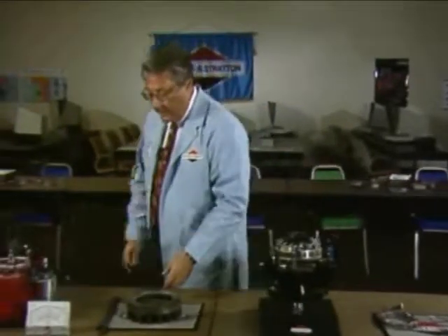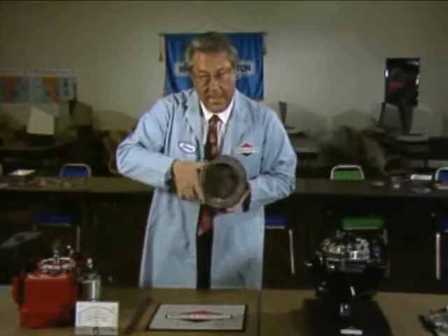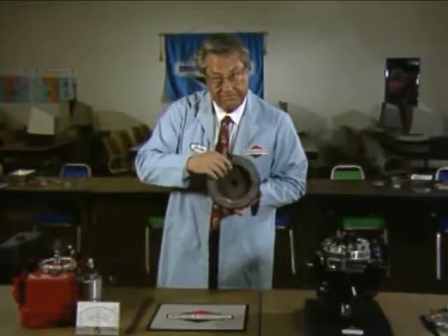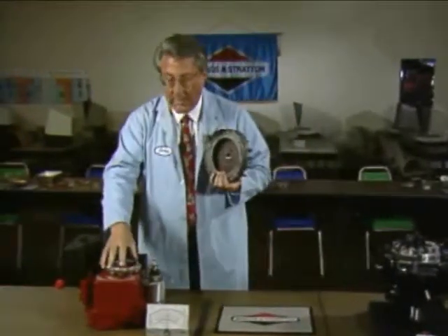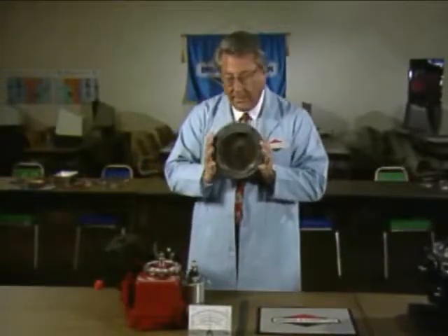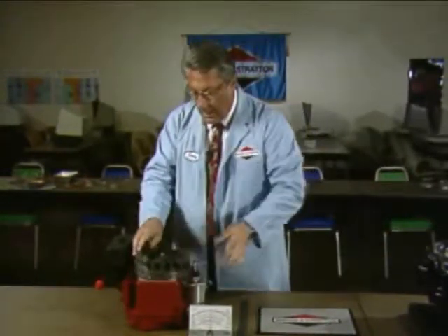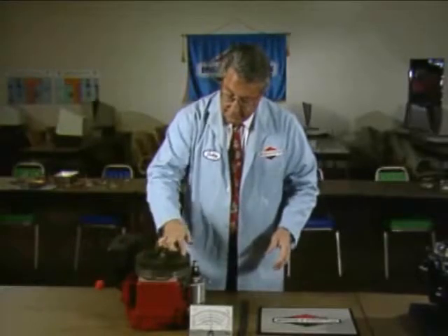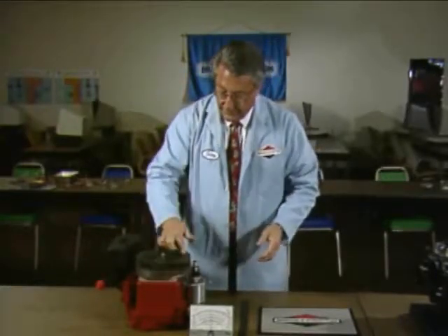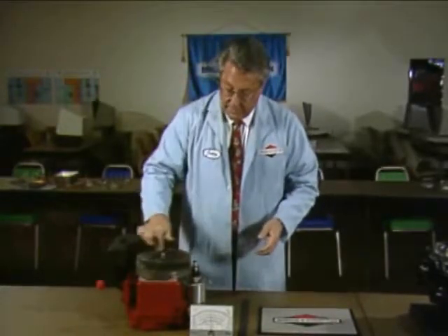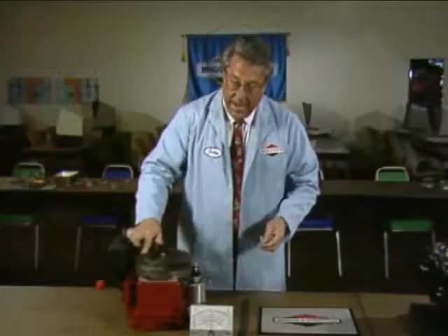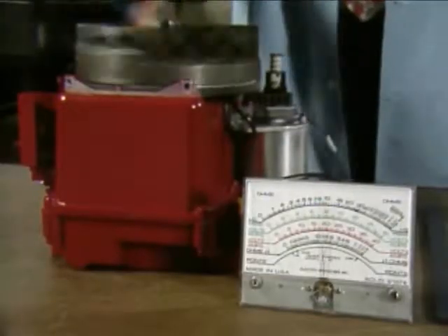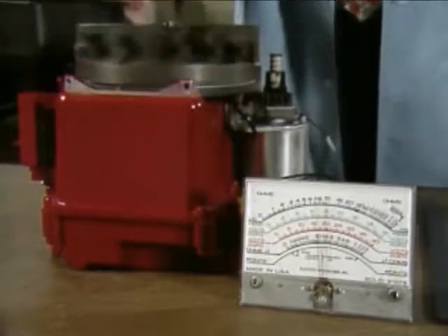used for the ignition system, or a continuous band or row of magnets underneath the flywheel. By attaching the coils directly to the cylinder and the magnets to the flywheel, we achieve the third requirement, or relative motion. As the flywheel turns, the magnetic fields pass through the conductors, stimulating the movement of electrons.